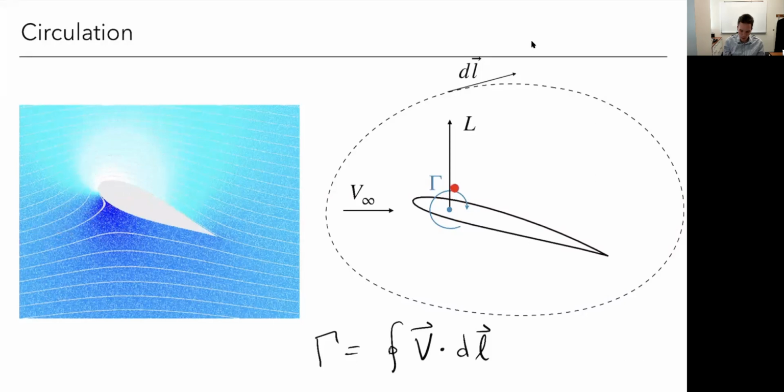So on the top, velocity is going to the right, same with the velocity going this way. So it actually speeds up over the top. And on the bottom, this circulation is going from right to left, which is opposite my free stream, so it slows down in the back. So I can adjust this properly so that I can get the right sort of velocities around this airfoil, okay? Just conceptually, right? We can actually kind of simulate this. We need a little more detail than that, but that's kind of the basic idea. And this spinning of the fluid, if you will, is related to the generation of lift.